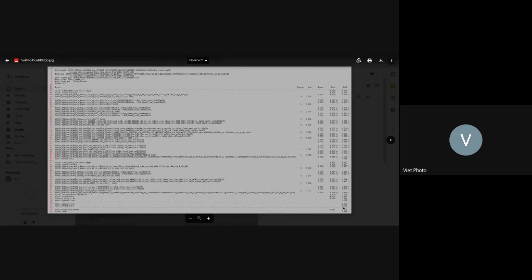That means it has a slack of 18 picosecond, so it is positive. It arrived 80 picosecond before the requirement, so this part meets the requirement. That's how they check the setup time. I will send this to you.